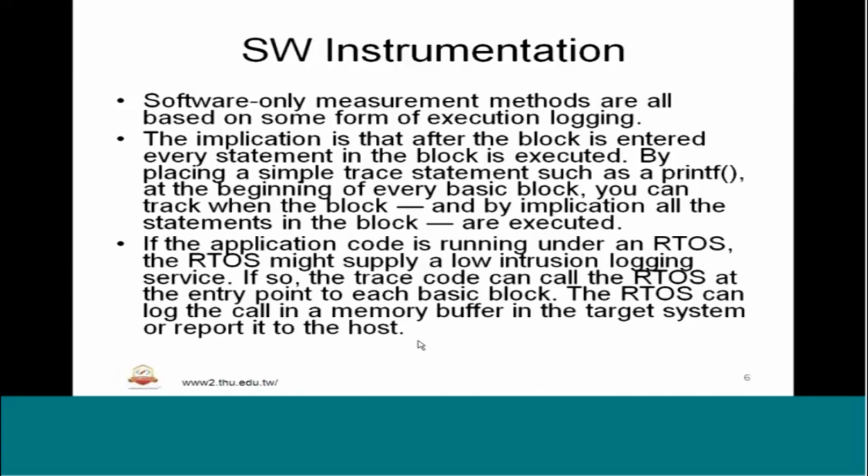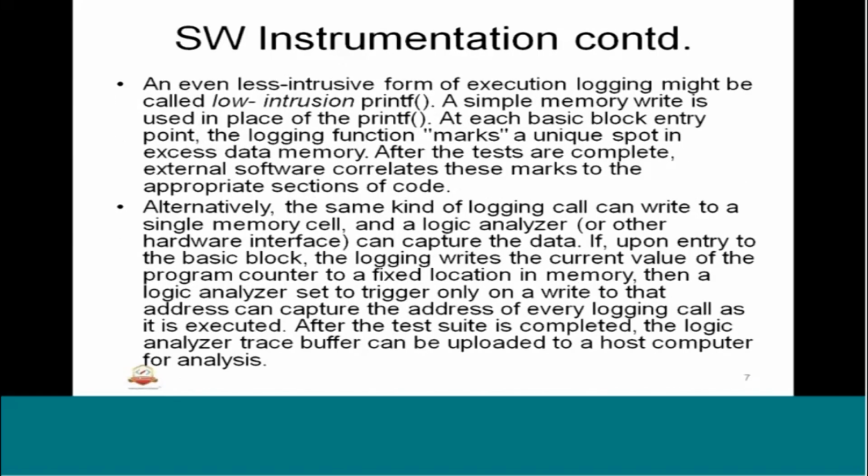A less intrusive form of execution logging might be called low intrusion printf, because it doesn't introduce much into the existing program. A simple memory write is used in place of printf. At each basic block entry point, the logging function marks a unique spot in the access data memory. After the tests are complete, external software correlates these marks to the appropriate sections of the code, so that whether the code is used or not used will be known based on the memory.